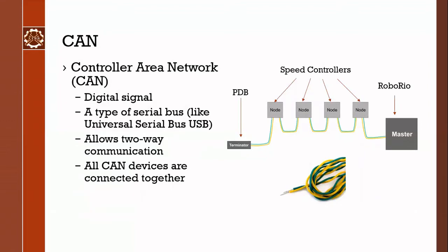So you basically connect everything in your robot with a single CAN circuit. That CAN circuit gets driven by, I think it's the master in this, which is the RoboRio. That thing can send out messages and code basically to everything on the robot through one signal line. And through that same signal line, those devices can then talk back to the RoboRio. This is much harder. This is a more recent thing to come to FRC. This is the same technology that's in cars and vehicles. This is what they use. It is much, much more powerful. It allows for some really advanced speed controllers.